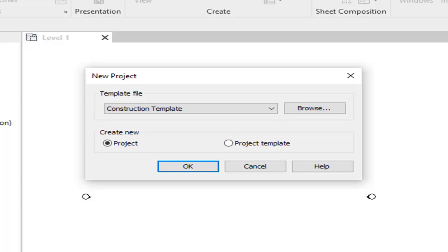Because prior to starting a Revit model, you need to have a template. You cannot go by the default template that you use, a metric or something. So you have to have an understanding, basic guidelines of what the units are that we are going to use, what the unit currencies are that we are going to use, how the schedule will go, what the color of the walls, pipes, and color coordination is, how the space will be. Everything would be laid down in the form of standards that would be put into the template.